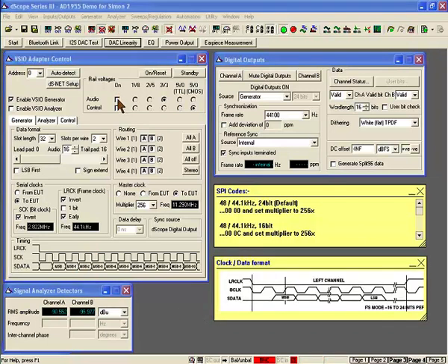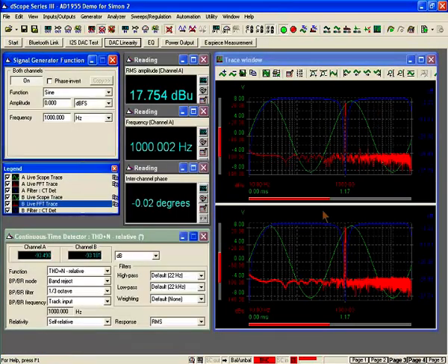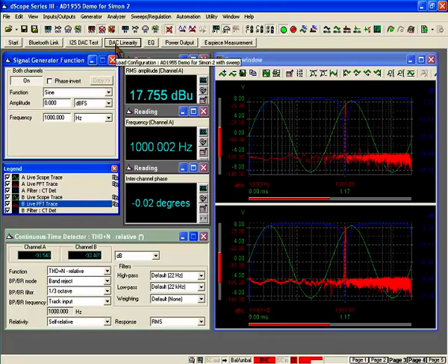So I'll just enable the serial digital audio data generation here, and my D2A converter has now come to life, and we can see here that we have a green sinusoidal waveform and a corresponding red FFT spectrum showing us the output of this D2A converter. There are many measurements you might want to make on your D2A converter to quantify its performance, and generally the starting point is the manufacturer's datasheet for that part to ensure that you have implemented the reference design or your own interpretation of the reference design without impacting on the performance of that component.